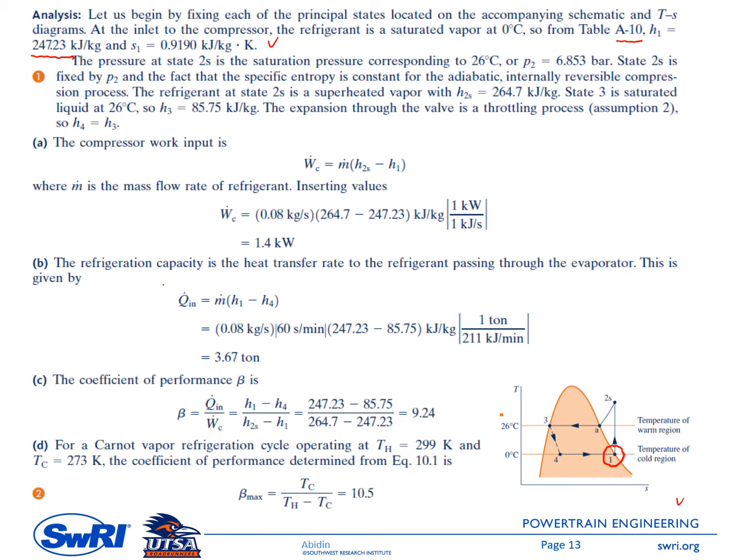Then go to state number 2s here. This is a superheated condition. P2s is given in the problem, I believe. P2s here equals the saturated pressure at T3.